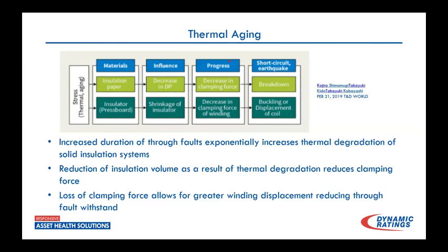You can do DGA testing, and that gives you a pretty good idea of anything that's happening long term in the transformer. You have partial discharge, or you have something in excess of 250 degrees C or 300 degrees C, so we're starting to see some ethylene development or gassing of that type of pattern. The problem with these events is they're so short lived, and without online monitoring, which I did not have a lot of at the utility, if you only have that sample being pulled once or twice a year, if you don't get out there